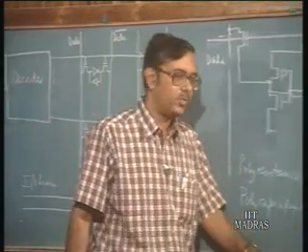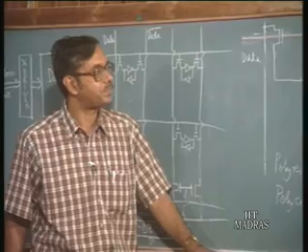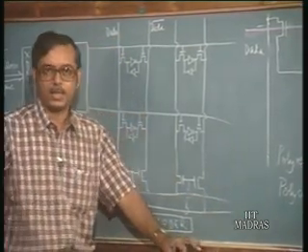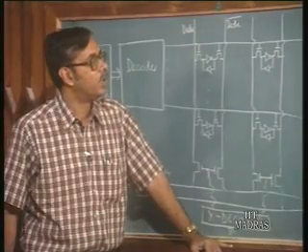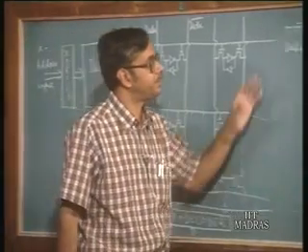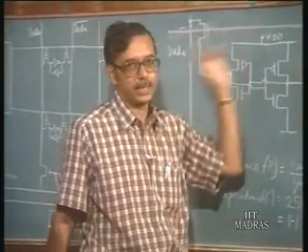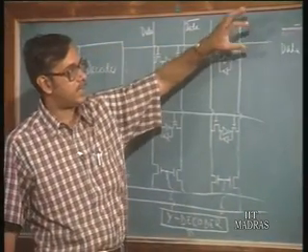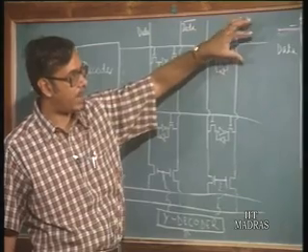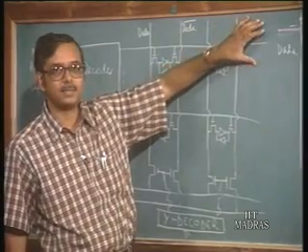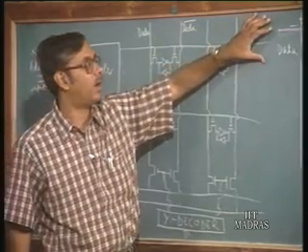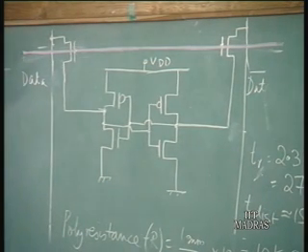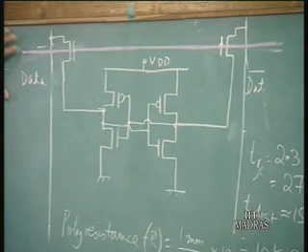We shall take it up when we look at bi-CMOS memories in the next class maybe. Now, this is one aspect of the delay, that is charging or discharging the word line. So, we require large devices, or circuits capable of charging or discharging large capacitive loads, to drive these word lines.